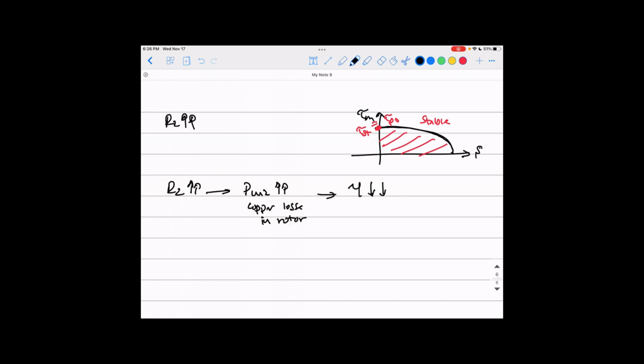So depending on different application styles, what do you actually want from your machine? If you want your machine to be as stable as possible, because you know that your loads can go much higher uncontrolled, you just sacrifice the efficiency and increase your rotor resistance. If your loads are stable enough and can be predicted all the time, you don't need to increase the rotor resistance that much, because you don't need that very wide range of stability, so you reduce the rotor resistance to increase your efficiency.